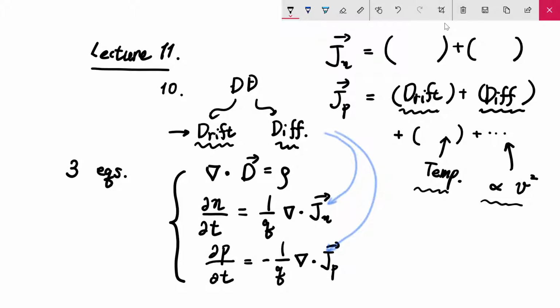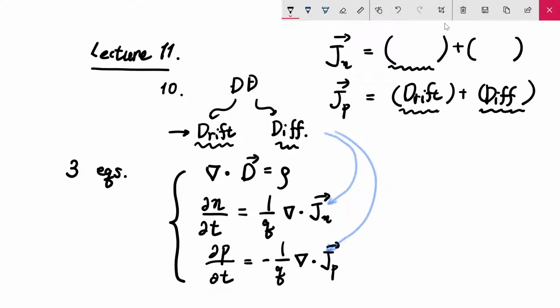Simply speaking, the drift diffusion model can be regarded as the simplest one among the family. We can sort different equations, and they can be categorized as one family. However, in this semester, we will just consider drift and diffusion terms, so all other terms are neglected. And if you remember correctly, it has quite a simple form, easy to remember: q mu n E plus q Dn times the gradient of n.